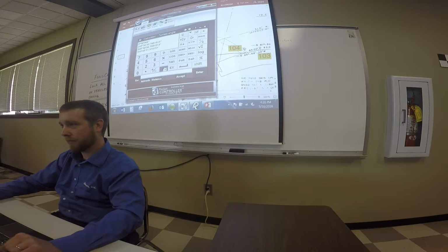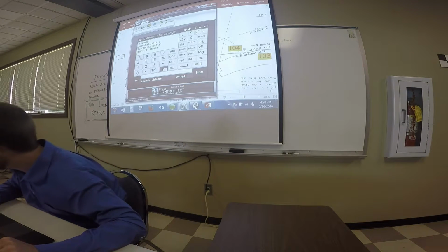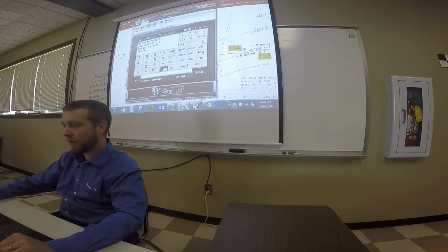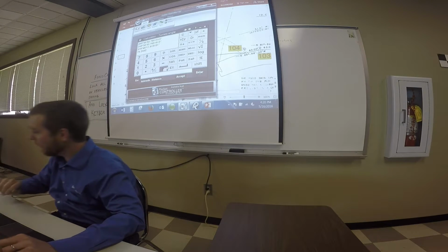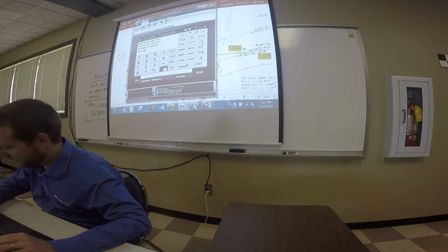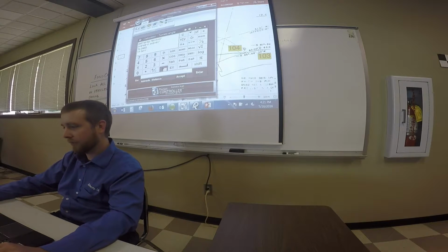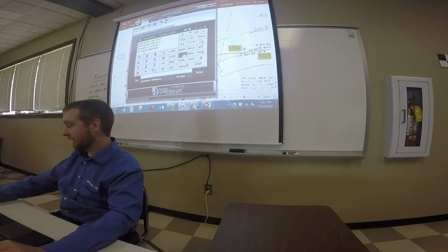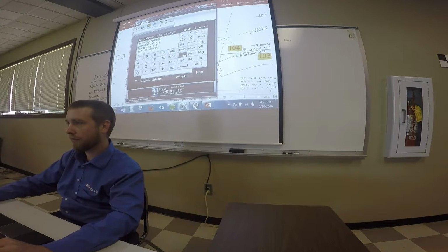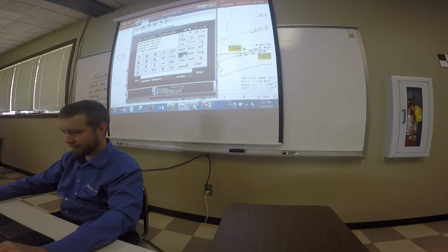How to use this? I think you hit enter, or like reverse notation. 4.2442, we'll enter that number in. And then we'll enter the next number, 17.3211. And then we'll hit the plus to add those, degrees, minutes, seconds plus. That's it, 91, 56, 53. Or you can also hit the button that says degrees, minutes, seconds if it confuses you.